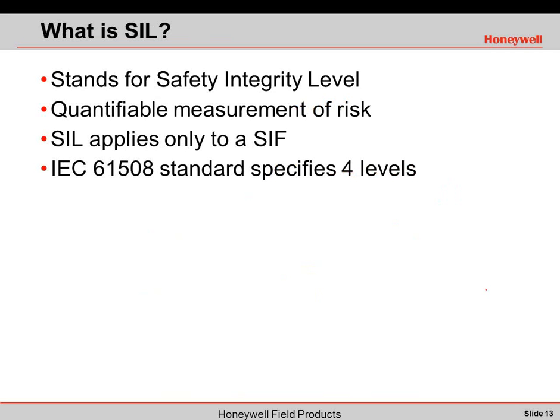And for the safety integrity level, there are 4 levels. So we have SIL 1 through SIL 4. And each of these corresponds to a range of target likelihood of failures, or probability of failures, of a safety function. And as I said, note that a safety integrity level is a property of a safety integrity function, not of the overall system.